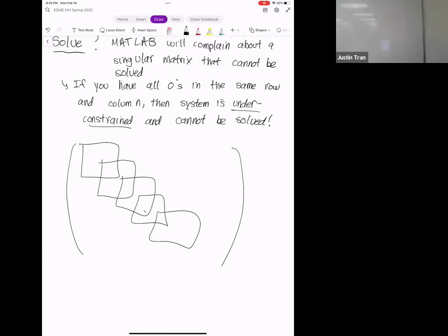Like this one's going to overlap with this one because you can see they're both F2 right here. And then this one's going to overlap with this one, both F3. It's just the same thing, you're just using different stiffness versions. And so for those ones, you're going to have a spring constant plus AE over L, and that's fine. They all have the same units, so you can have them together. Initially they just look scary, but it's just the setup. This looks wild, but that was a new one that I made up just for this.